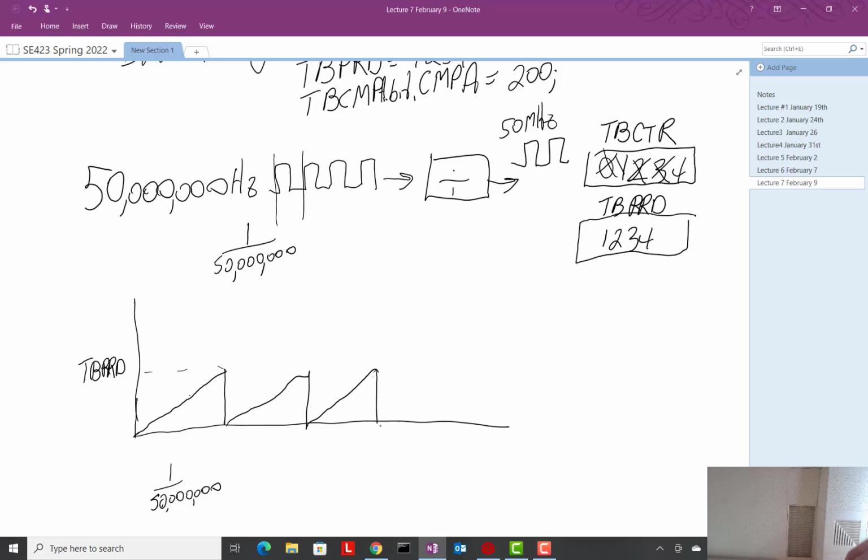Okay. Now, we're almost there. So, Kinga, to your point, what if I wanted to make a slow PWM signal? Or slower, at least. I could change this divide, couldn't I? If I change the divide, then the amount of time it takes to count up to 1, 2, 3, 4 would be, say if I did divide by 2, it would take twice as long, wouldn't it? Or if I set it to 3, it's a divide by 4. It would take 4 times as long, or whatever, right? So do you see, that's why you need to write to a register to make those changes. That kind of answer? Okay, good.